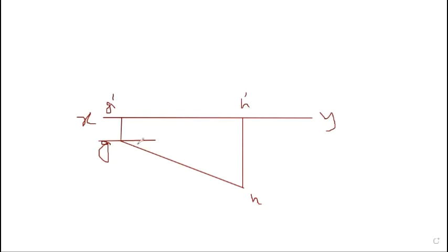And when you give the dimension, now if we draw the dark line, this must be darkened. This part also must be dark. So this is the top view, this is the front view. And when you give the dimension from this, because this is 45, draw a 45 degree line. Here also draw a 45-degree line.